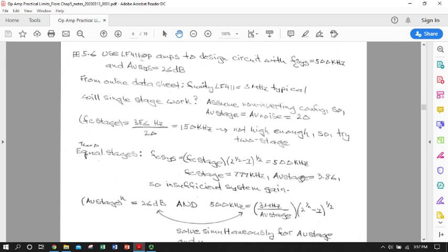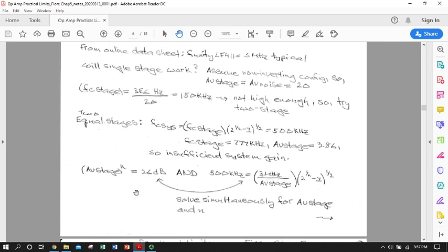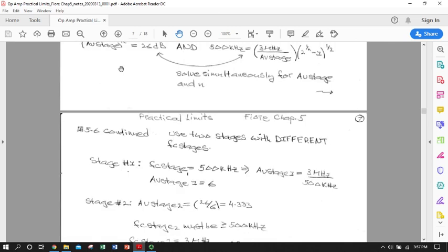And this is the result of that math. So we're calculating FC stage based on our gain needs, and then dropping it into the two-equal-stages version of our system with equal upper break frequencies to get the upper break of the system. Can't do it. That doesn't work, because we'd have to solve these together. So we end up best off using two stages with different FC stage.